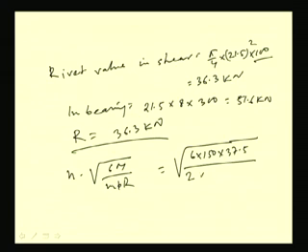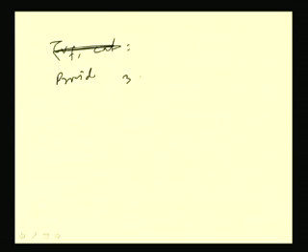M, 2 rows we are using, say let us use pitch as 60 and rivet value at 36.3. So from this I am getting 2.7. So, 3 numbers of rivet we can use. Provide 3 rivets in each row.